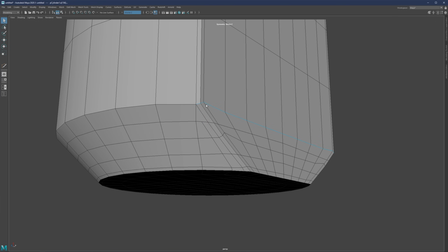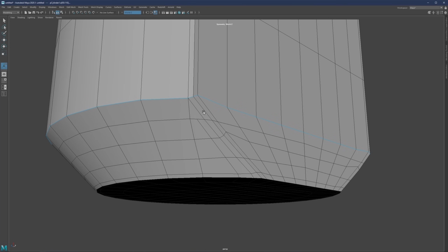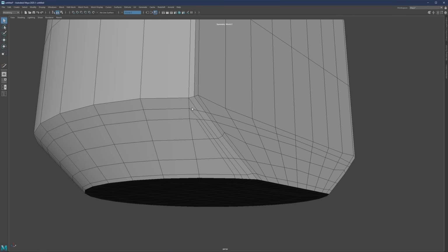So to do a support loop, we can just select this part, turn the chamfer on and do it like this, but you can notice that we have some strange thing going on, and the alternative would be that we create one manually like this. So this is now our support loop, and basically this edge should then go here.